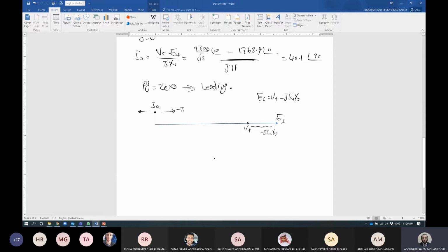So here, because we don't have any power, power equals 0. We mean electrical power for the motor, which is P. Power equals 0. This means delta has to be 0. And you know the relation of power equals also V terminal IA multiplied by power factor. And you know the expression of minimum current means the power factor is what? Unity, exactly. We have V terminal, it already has a value.